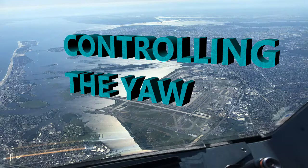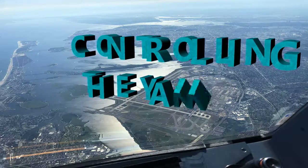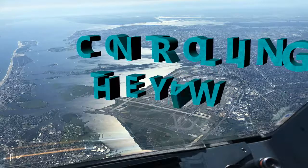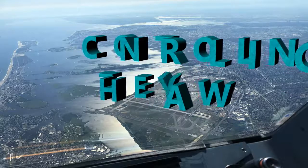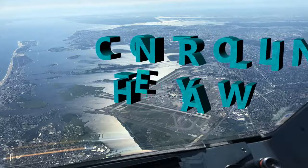So that's one way. That's what it's doing. Now, the Autoflight system can be either engaged or not engaged, 2 choices. If it's engaged, then it does everything I just said. If it's not engaged, then we have the other option where we still have control over what I just mentioned, but in a different way. This time it's through side sticks and thrust levers. Just a side note, if the Autoflight system is engaged, then you're not going to have an actual automatic movement of the side sticks and thrust levers. It might seem like it's going to move, but it does not. You may want to note that somewhere in your notes, because you might see that on a test.